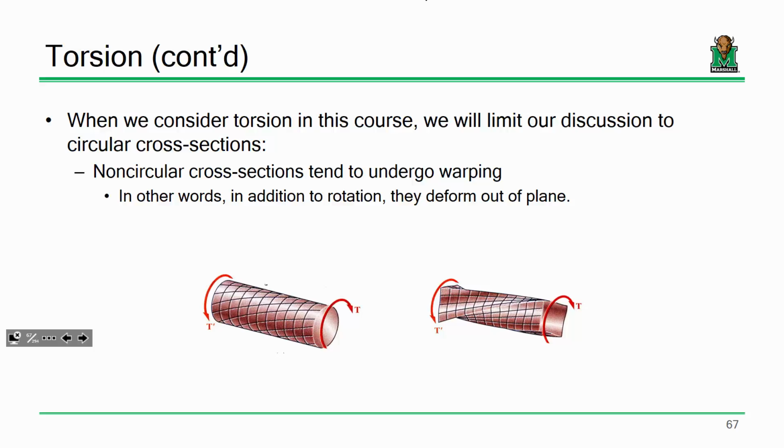You mechanical engineers who are designing mechanical components can almost guarantee 999 times out of 1,000, if you're designing something that is meant to be twisted, it will be circular. Because it's going to respond in a predictable fashion. It's going to be easier to fabricate, easier to put together, and things in torsion are circular. Let me say it like this: circular segments respond to torsion in the best fashion. They're the most efficient shapes to resist torsion anyway. So, okay. Everybody good on that?